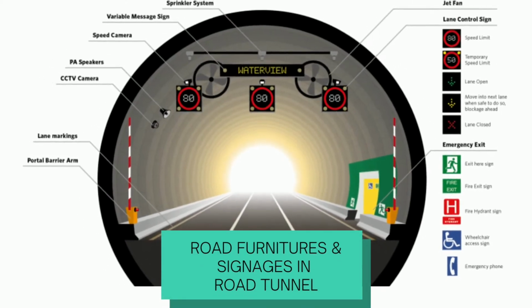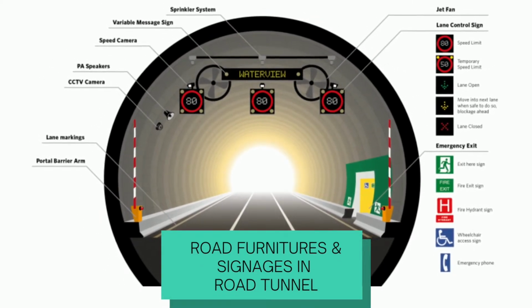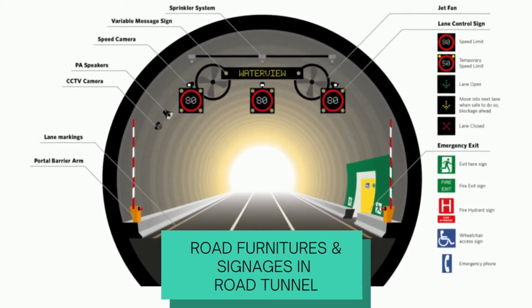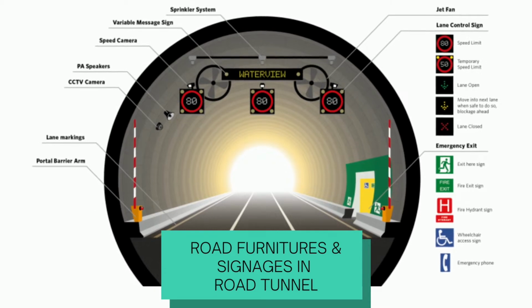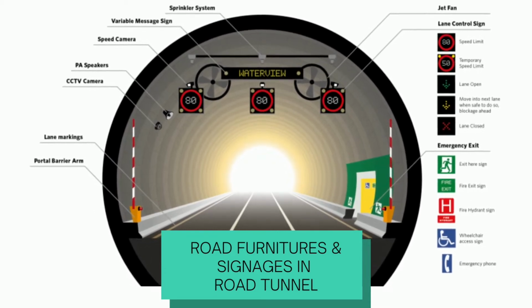Usually for transportation tunnel, it should be constructed with a complete system. The tunnel should have road furnitures and also road signages. Here we can see the tunnel being constructed complete with lane control sign, suggested speed limit, CCTV, emergency exit, emergency phone, and many more. So a complete constructed tunnel will simultaneously provide safety to the consumer.